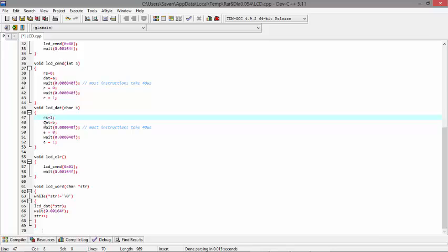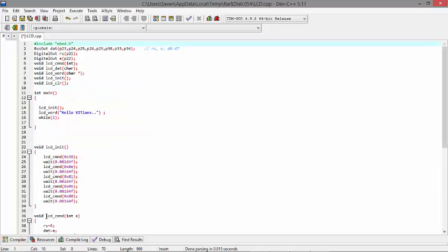So it will go here, that variable name data, and consider it, and these are my enable 0 and 1 pin. And again it will come back here, wait for some time, increment the string, and one by one all the data that I give will come and print on the display.